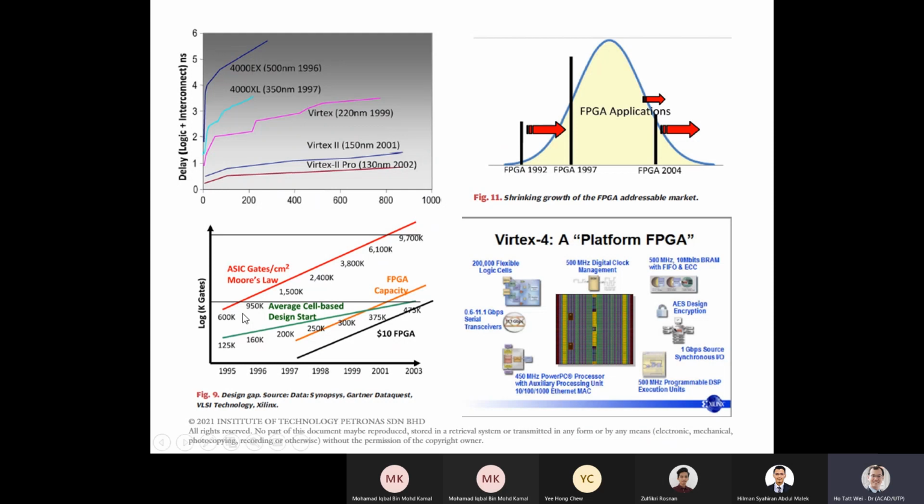And so we are now going to see that there's an evolution of FPGA. In the early days, it was just about programmable logic. Can I just implement a combination of logic? Then as time goes by, they tried to cram in more and more logic, and gave you more power to create more and more sequential state machines. And after a while, when the capacity of the FPGA grows so big, at some point there's a shift where instead of adding more programmable logic, they start putting in customized, fit-for-purpose circuits. So FPGA today is not really like the FPGA from 10, 15 years ago.